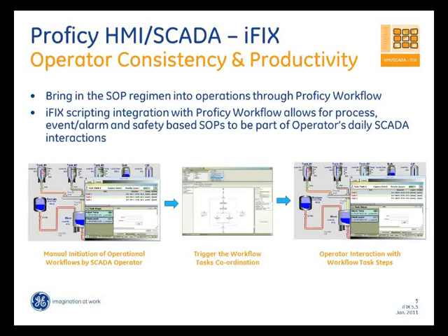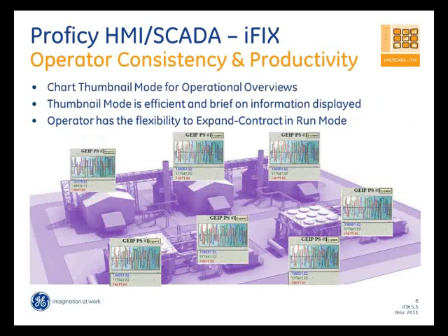The other aspect is related to charts. We introduced this chart object when we did iFIX 5.0, but we have done several enhancements to that chart object. The first feature is really introducing a thumbnail mode for that chart object, so you can have a small thumbnail of a chart which basically updates as data comes in on your screen, and you can have multiple of these thumbnails on your screen.